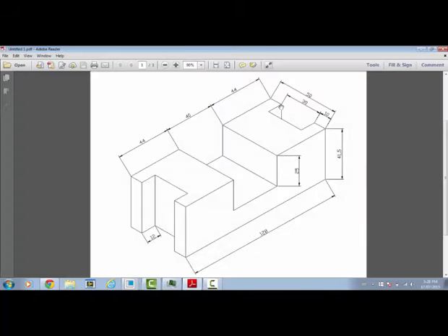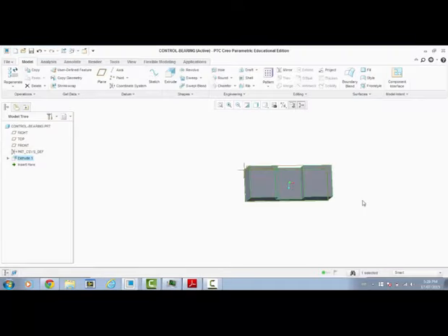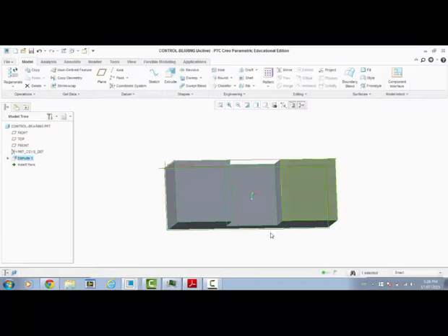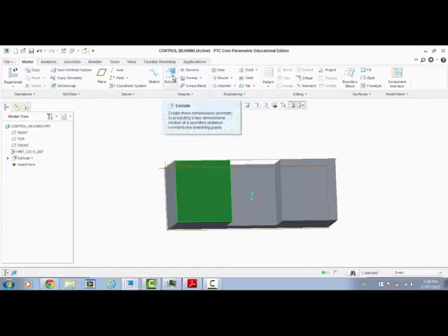So now we'll go back and look at the object again. We'll look at the top view, and we have to draw this notch in the top view at both ends. It's 12 millimeters deep. We know that it's 50 millimeters wide. It's 10 on each side, and it's 30 millimeters in the center. So going back to our drawing, we have our top view now to draw, and what we're going to do is choose this view to draw on.